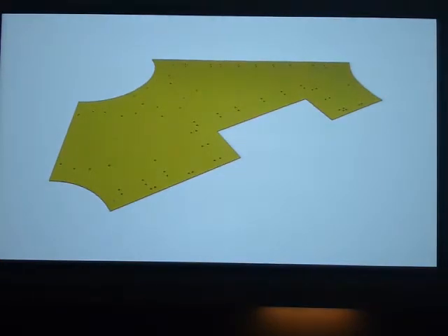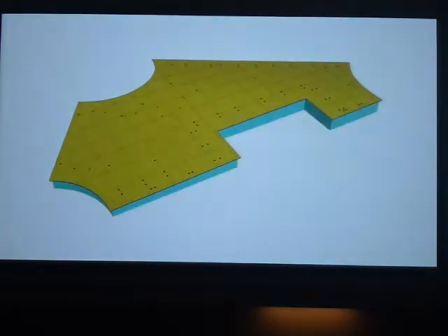And we add the locations to the provided CNC file. And the surfaces for the template are created automatically. The panel information is then in turn turned into a dimensioned 2D drawing that can be used to check all dimensions, as well as a 2D drawing to check all locations of the studs.